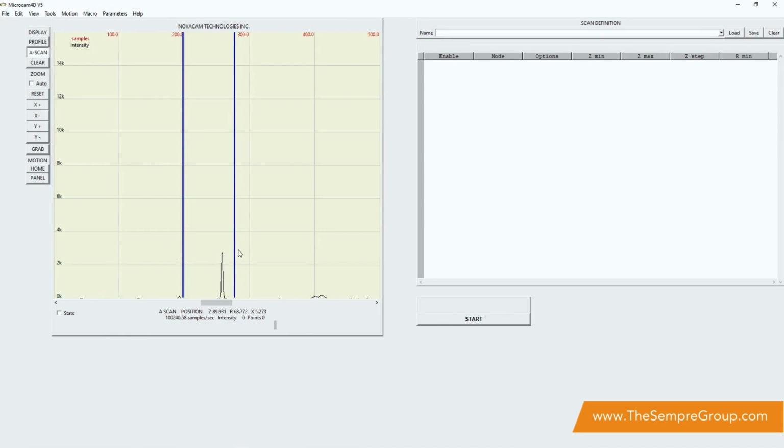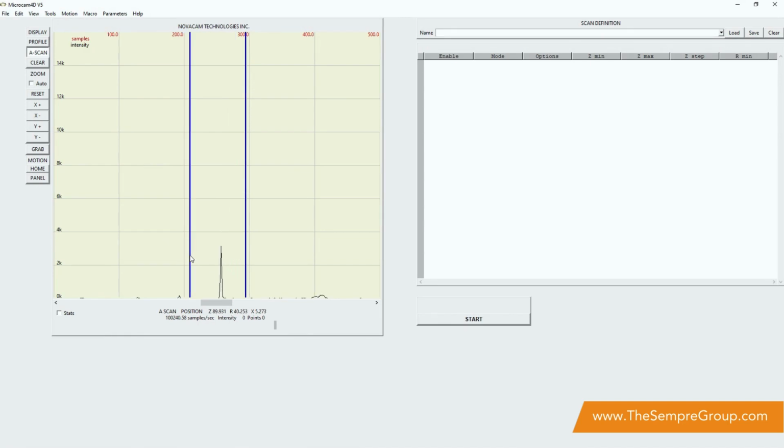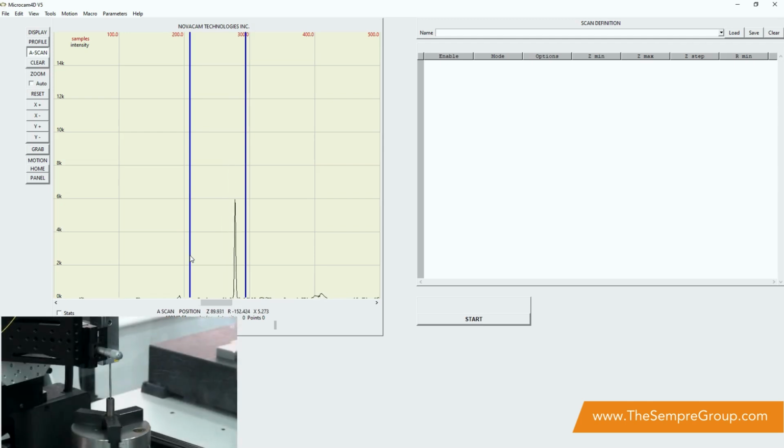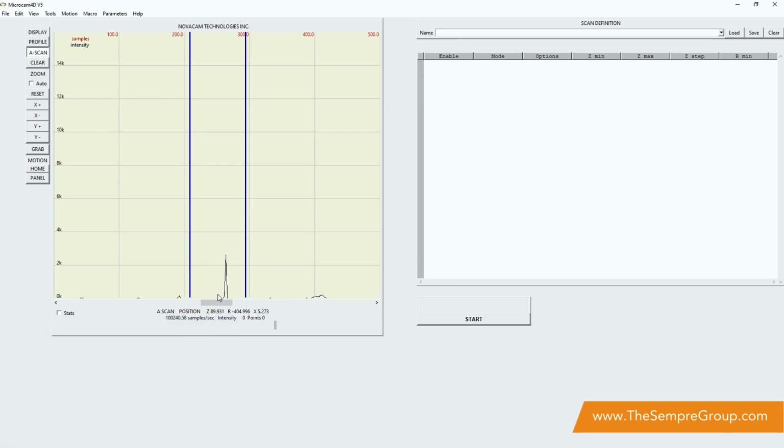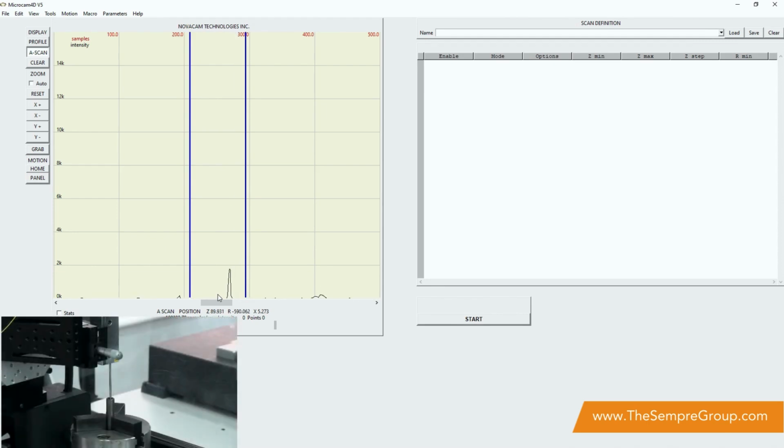What I'm going to do is refine the position of my blue boundaries so that as I rotate, this signal is very close to those blue boundaries. Effectively what this is showing is on the bottom level where our zero is, if I show you with the mouse, this is effectively our ambient noise. So you can see that constantly the sensor is finding data and what we've got here is our initial contact with the surface. So as we rotate round, you can see that the signal's changing.